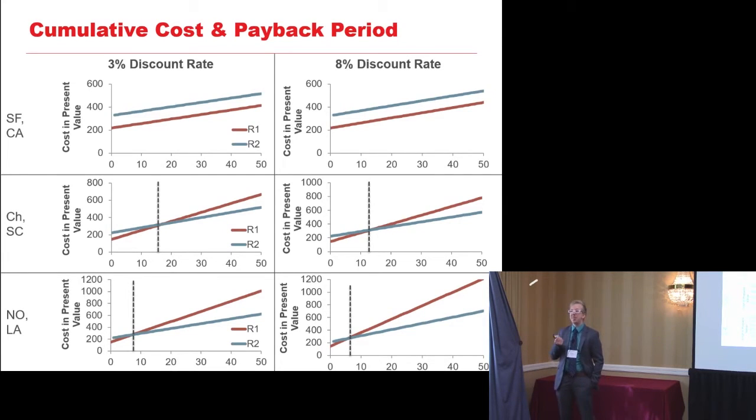So it's also specific to this case study, wherein all they did was put additional nails in the shear wall for that particular housing type. A challenge with earthquakes, the way that buildings are designed to withstand earthquakes, is really, since they're so unpredictable, they just want you to get out of the building, and the building can then crumble. That's how the current codes are based. Versus hurricanes, you have a warning, there's evacuation, so they're designed for a different type of resistance. And so really they want you in hurricanes for your buildings to flex a little bit under the load so that you can run out the door.